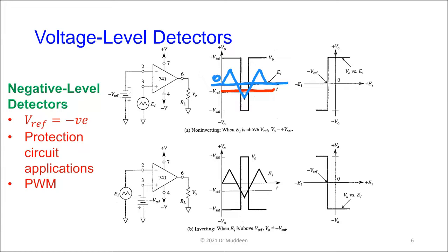Oh, I had thought that it was offset or shifted up, because you had a vertical line there. I didn't see that it was actually 0 at the reference line. Right. So the inputs here, this line here, this is 0. We're going symmetrically above and below 0. You could gather that if I put a pure signal in on the op amp, there's no reason to assume that the signal would be offset like this, not unless I deliberately want it to be like that.